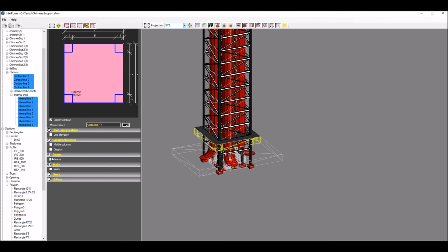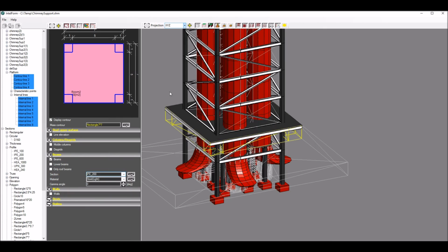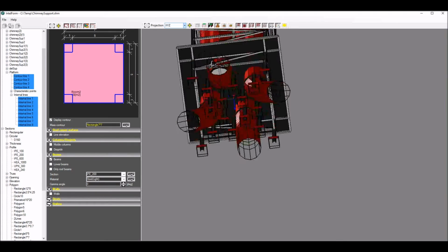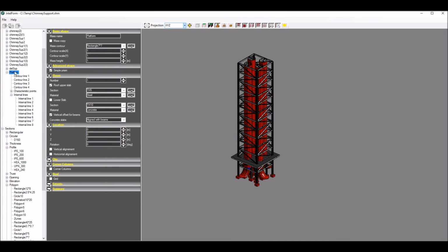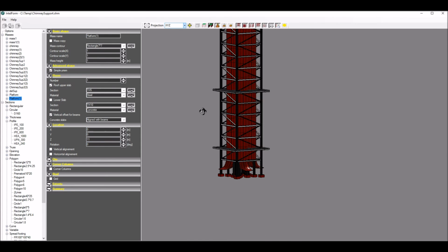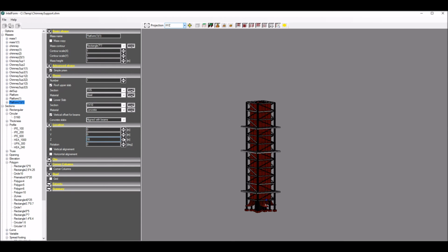Here I use this possibility to set beams for all these lines. I set an appropriate section for them and platform parametrization is finished. In the tree review, we can easily verify if the achieved effect is consistent with our intentions. Then we can just copy this platform to other locations. If I would like to change some of the original platform parameters later, it would be more convenient to explicitly define these copied masses as copies of the original mass using the mass copy option in the basic shape group. Then they would automatically follow all changes in the original mass.